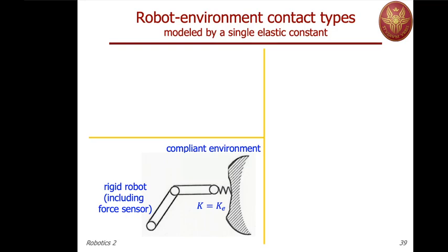When dealing with force sensors, with the physics of measuring forces, we have seen that we need the deformation of the internal structure of the force sensor. We mount strain gauges, and through that we have an estimate of the contact forces. So some deformation is always there.